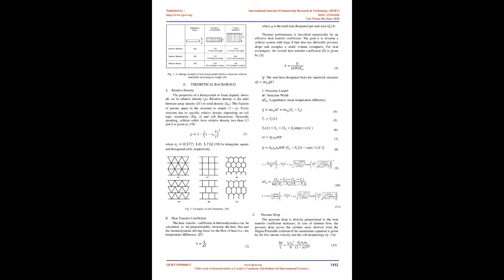1. The main concern of this paper is metallic sandwich structures, especially with corrugated hexagonal cores. They show promising performance in multi-function applications. When compared to regular solid sheet metal with the same weight and material, corrugated sandwich structures performed better under controlled blast too. In this thesis, a further investigation of open-celled corrugated structures was made to highlight their performance as compact heat exchangers. As they allow a continuous flow of fluid, corrugated structures are ideal when a rigid yet light heat exchanger is needed.